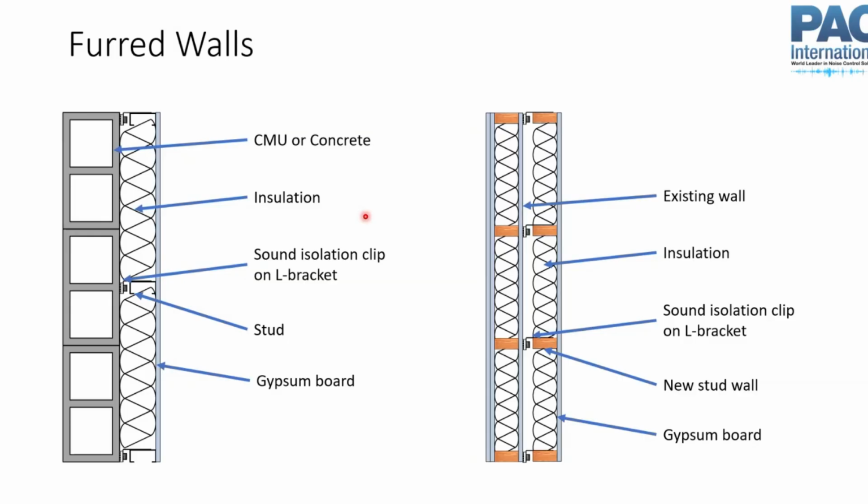And you have an existing wall that's already there. That's part of the existing base building. It's fire rated. You don't really want to touch that. So you need to add something to it. Maybe you've got a fairly tall wall, and if you design studs that could just do the whole clear vertical span, you'd need heavier gauge studs or thicker studs that are going to take up more space. So if you can tie back to the existing structural wall, you can reduce the size of your studs or the gauge of your studs or whatever it may be, and maybe save some cost and save some space. So you want to tie it back.